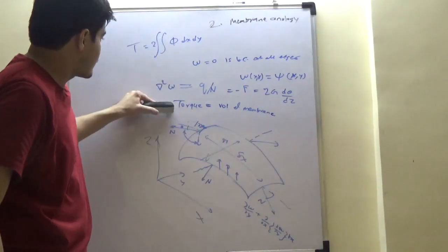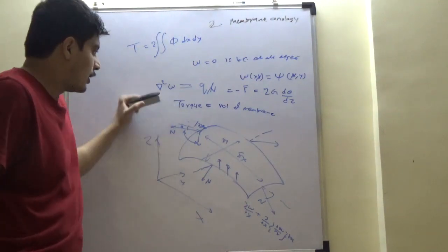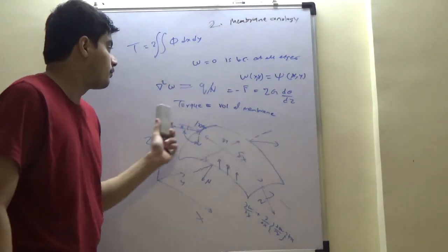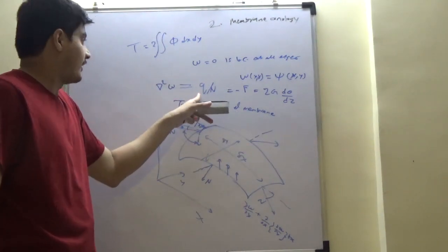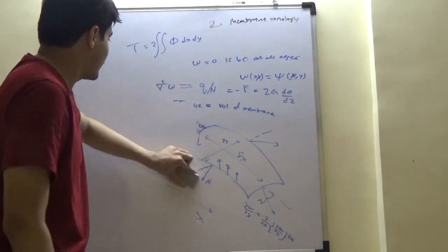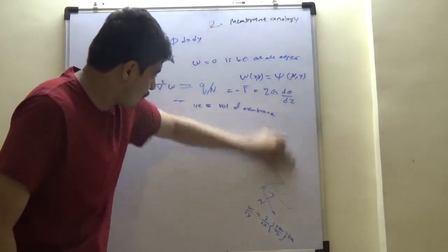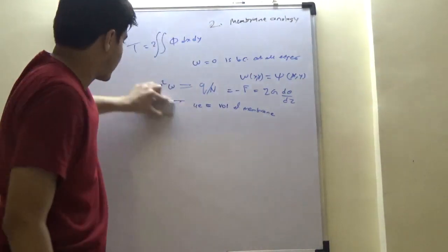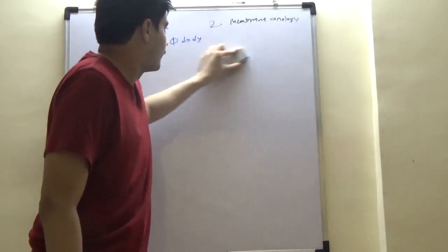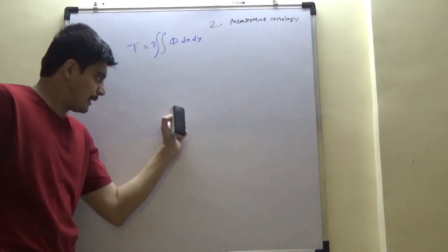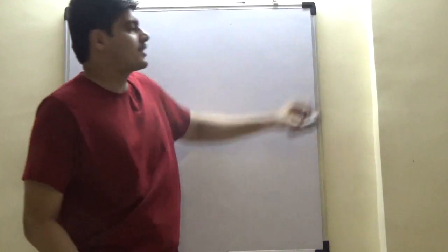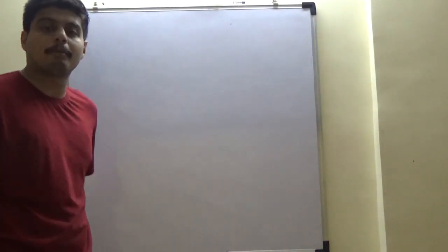So you have transformed a first set of problem into completely different physics of a second problem, which are mathematically superimposable. This is much easier to handle, right? Because unit loads Q by n are very easy to handle without looking at any other complexity. So you have transformed your physics problem into a mathematics which is repeatable in other physics with the same consistent solution, and you can transpose back W as psi and solve your torsion problem. So that was the membrane analogy, a very powerful analogy by Prandtl.